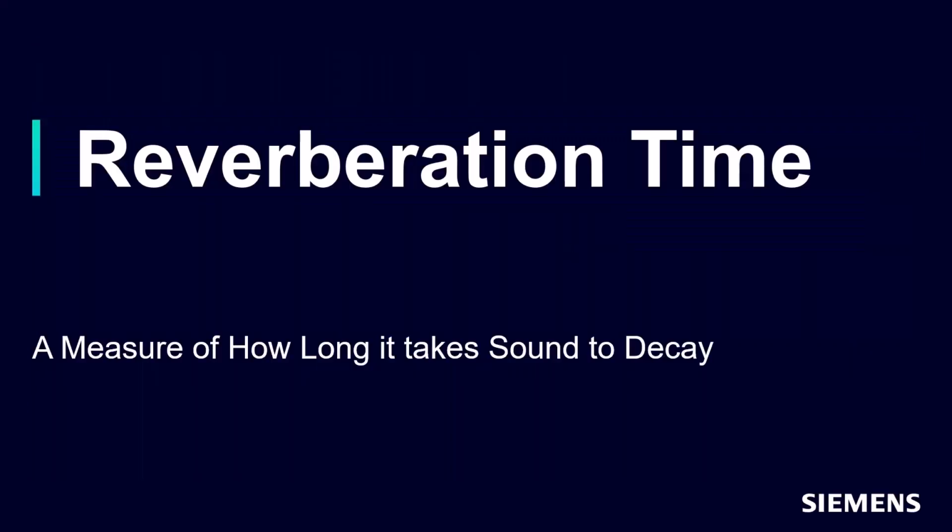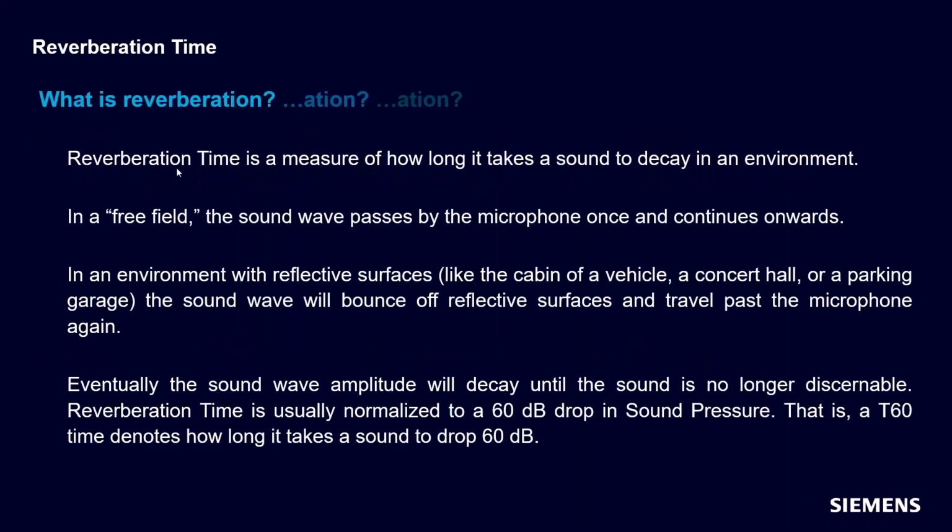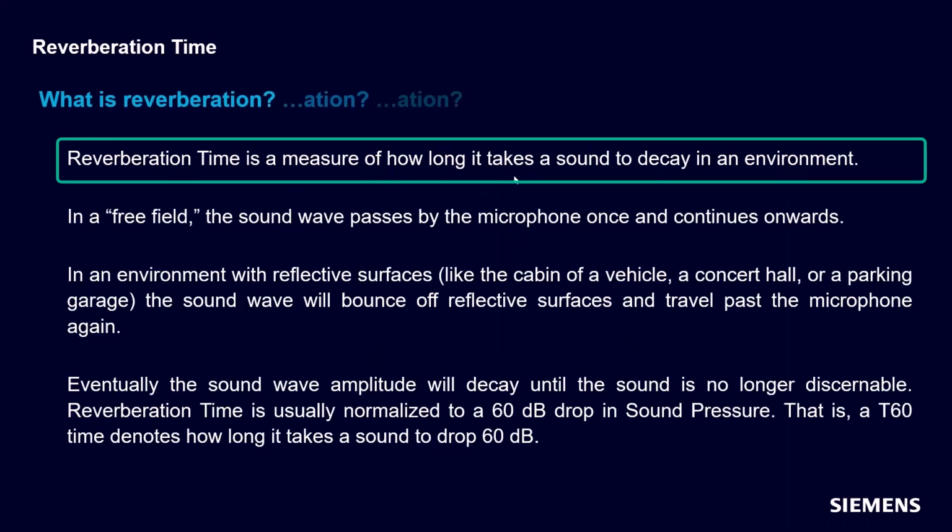Now that we've gotten those basics out of the way, let's talk about what reverberation time is. In really basic terms, reverberation time is a measure of how long it takes a sound to decay. Think of standing in a big empty parking garage and yelling, "Echo," and hearing those echoes back at you and trying to count and see how long it takes those echoes to attenuate to where you cannot hear them anymore. Reverberation time is a measure of how long it takes a sound to decay in an environment.